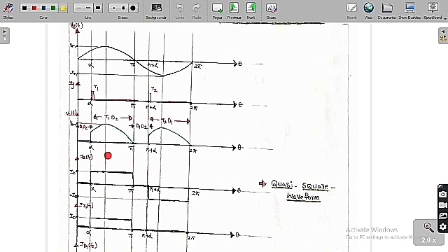So for the asymmetrical and also symmetrical circuits, both the graphs of the output voltage and the source current are the same. They are the same as the previous circuit. Only the operations of the thyristors and the diodes are going to change, but everything else is the same. Now this graph we are going to call the quasi-square waveform.